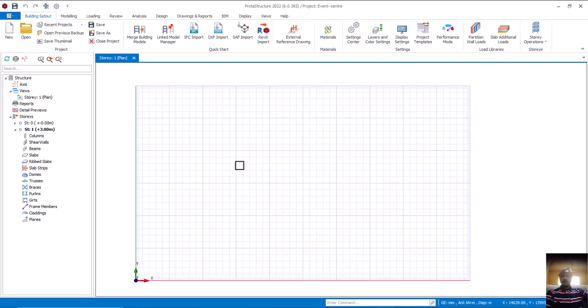So once you open your software, whichever one you are using, especially Protastructure, be it Protastructure 2018, 2021, 2022, or 2024, and also the latest version presently, as at the time I'm producing this video, which is 2025, whichever one you are using, once you have gotten to this place, the next thing to do is to import your DXF drawing that you have saved. So I'll come to this place now. Under building setup, I'll come to external reference drawing. I'll click.